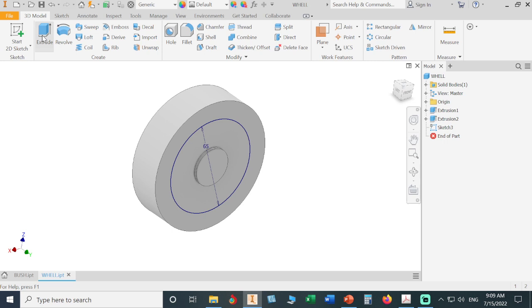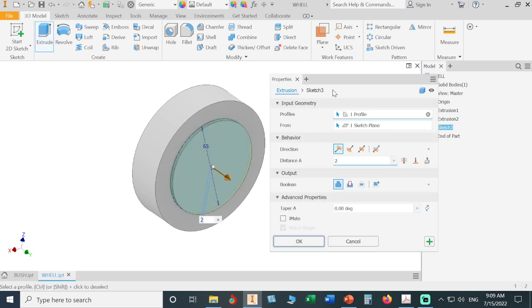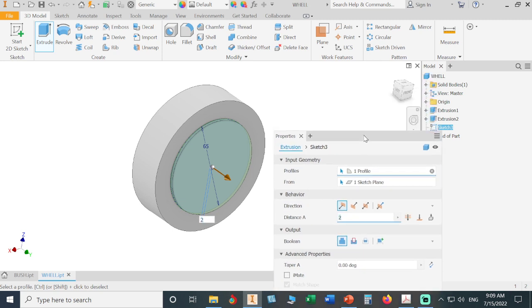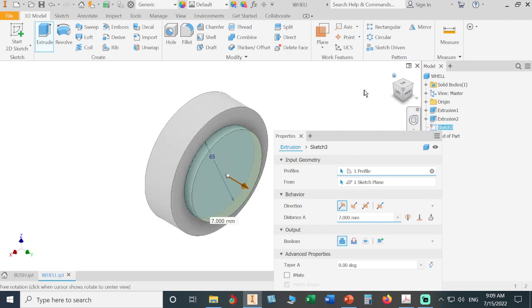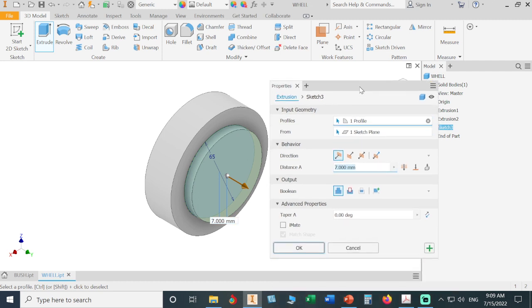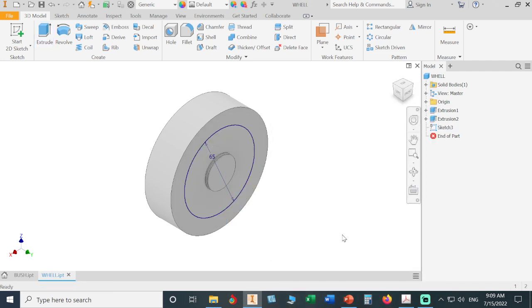If I give it extrude, it will take all the 65. What I want to mention also, is that the extrude tool adds material or cuts material perpendicular to the face only. This is not what we want. We want to cut between circles, then cancel. What shall I do now?